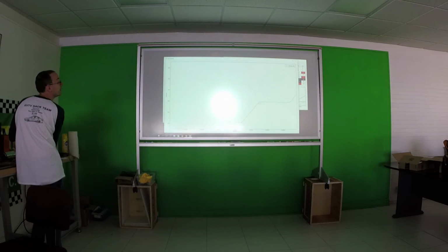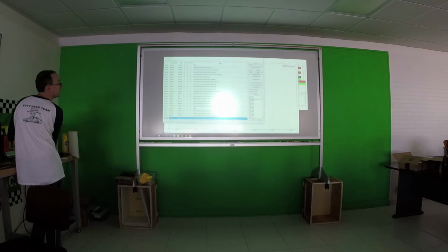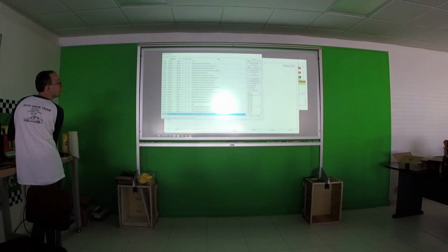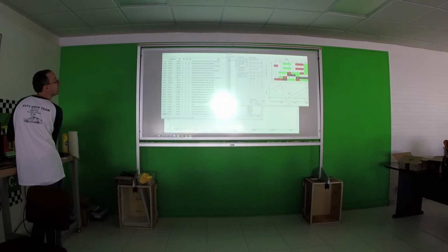And once again, with the graph window, let's say I'm looking through here, and I wonder what's going on right here. If I double click that, that's selected on this window now. All the windows kind of synchronize that way, where if you click in one of the three windows, it'll automatically bring up the data in the other windows. So even the flow view here should have automatically updated to what I just clicked on in the graph. And then when I click here, the graph will also move automatically, showing me the current position of flow view. So that helps you to look at multiple windows at once and correlate what's going on.